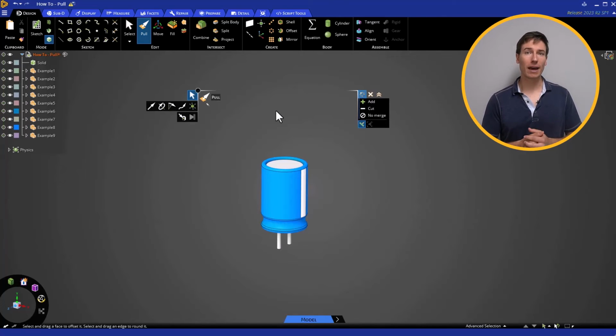At a higher capacitance, the component will be larger, but keep the same general shape. To begin the operation, select the Scale option. Then choose a reference point as the anchor point. The body will scale out or in from this point in all directions. The world origin is always a good option, but a point or vertex will work as well.